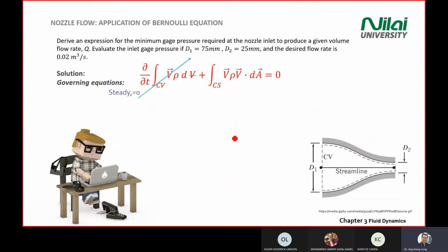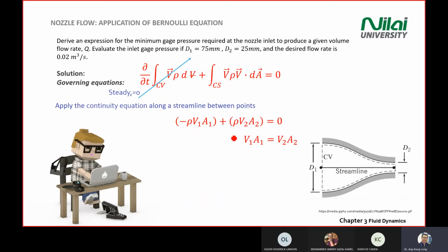Then the next is just application of what we have. The next one is finding the Q. Applying the continuity equation: what I mean by continuity equation is that m dot is the mass flow rate. When you see the continuity equation, it means that you're finding m dot. M dot is rho AV. Take the density times the area times the velocity, you get mass flow rate.